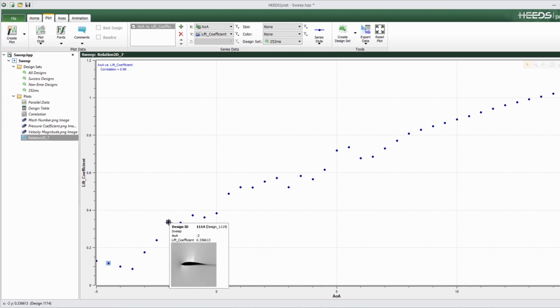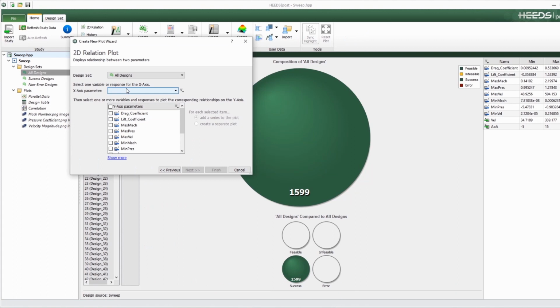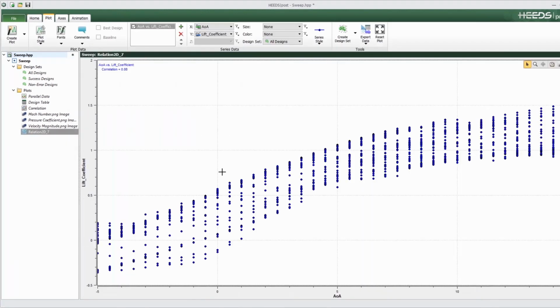Design Manager allows for multiple cores to be dedicated to each simulation or several simulations to be run on individual cores simultaneously. For the best use of parallel efficiency, in this case, 12 simulations at a time will run on one core each. In total, the 12,792 simulations took around 80 hours, equating to 270 CPU seconds for each simulation.